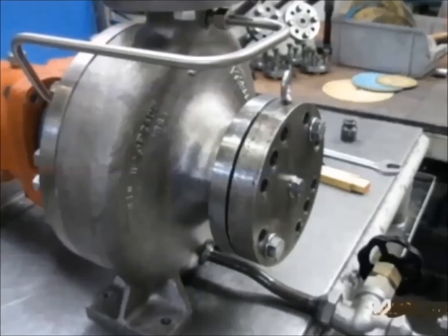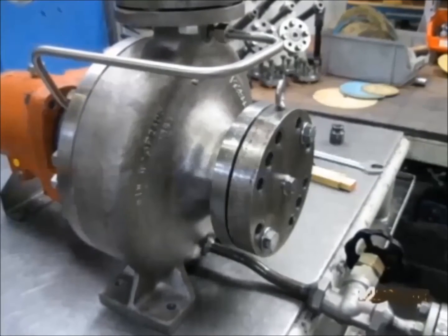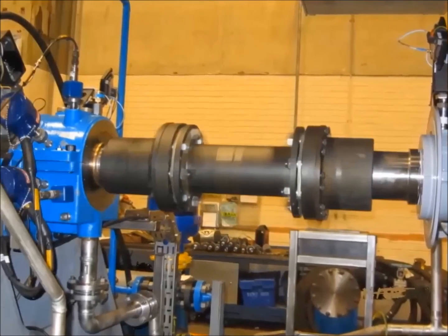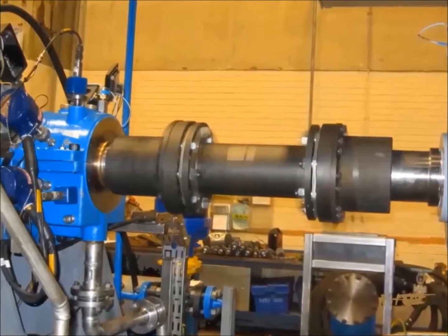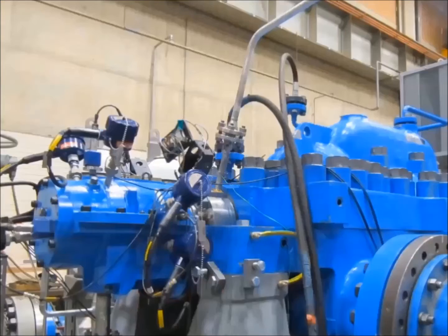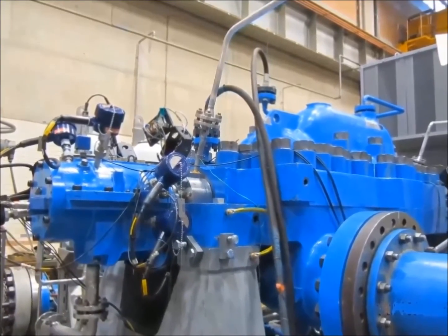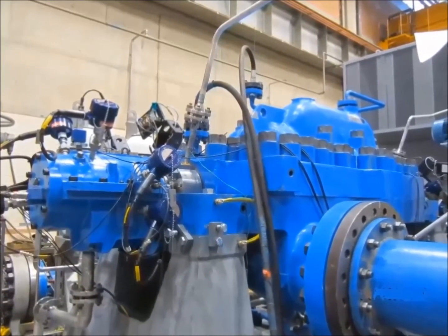As stated above, the factory acceptance test is terminology that is widely used by vendors. The FAT is all required tests, which are included in the inspection and test plan and must be done by the vendor. The FAT is conducted to determine that the equipment operates according to its construction code and purchase order specifications and covers functional requirements.